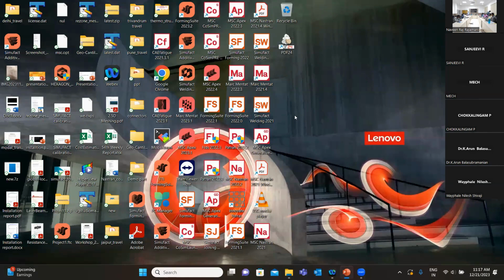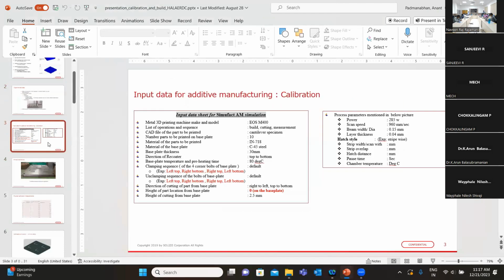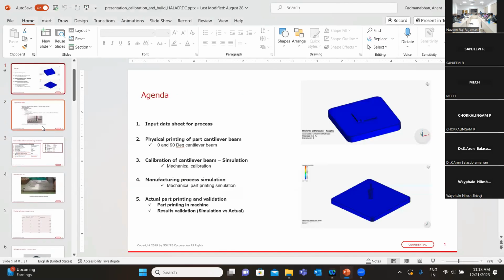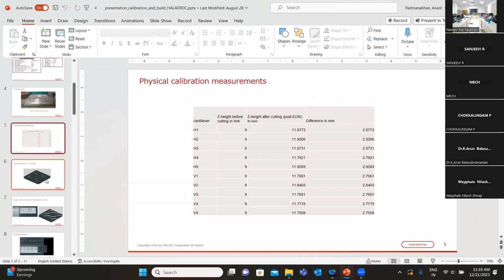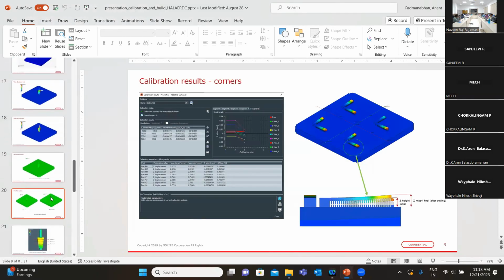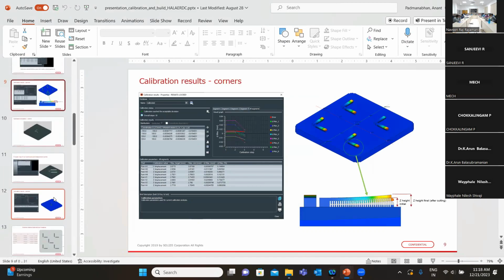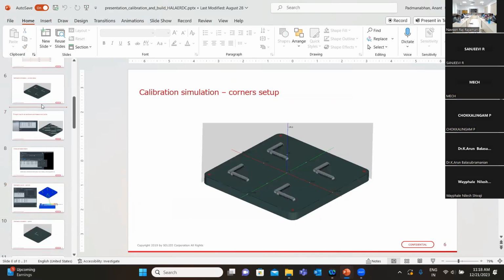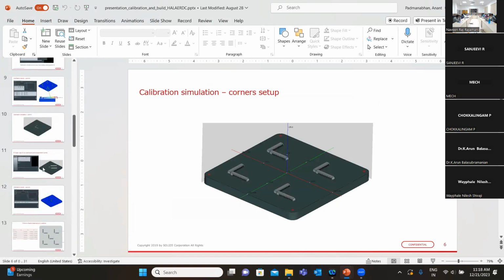For powders, we have laser bed fusion, right? Similarly, the machine itself has the furnace. So once you build up the specimen, you can directly give how long we need to give the heat treatment. That is also possible. So within a single attempt, when you upload the file, whatever you want to manufacture in the STL file, they will build it, do the heat treatment, and give it back to you. Then finally, if you want to go for further processing like machining, you can go for it.